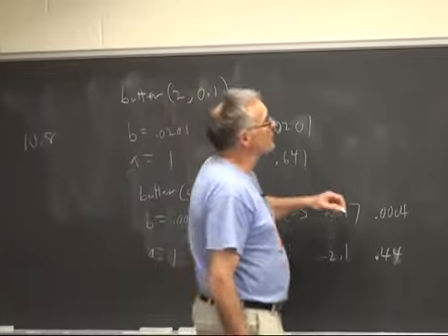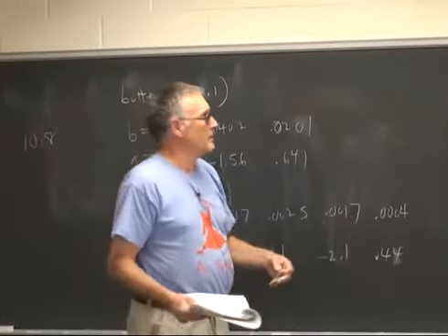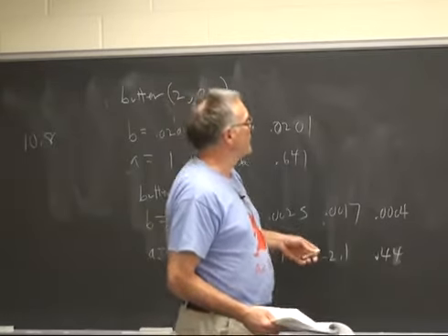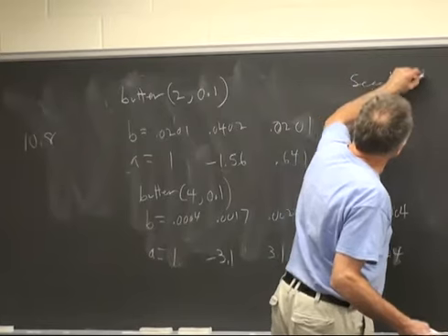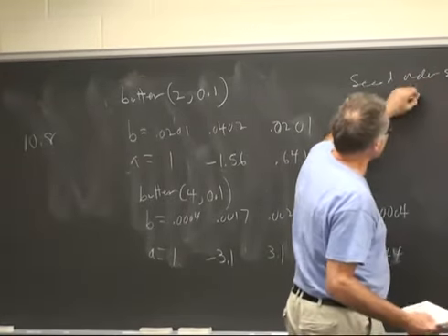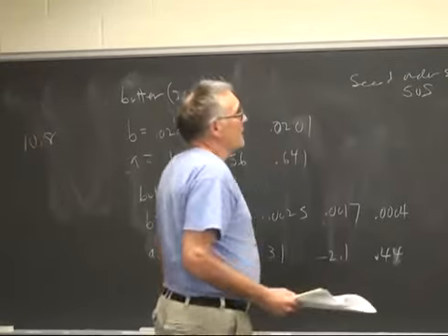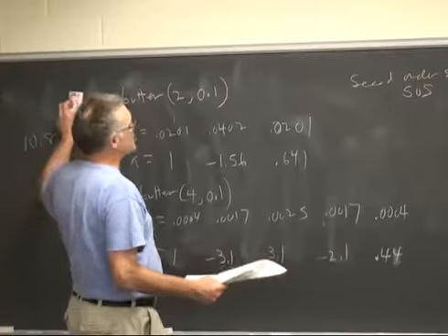And so what we're going to do is factor the filter into second order sections, so-called SOS.